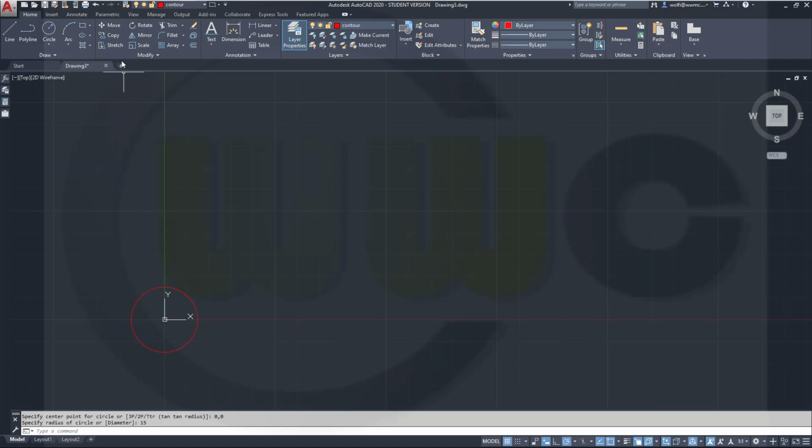Therefore I want to copy that circle. So go for copy, select that circle, right click to confirm the selection, and then you could click anywhere like this, and as your polar tracking is on, you can move along that trace, and the distance along that trace should be 60, and escape or return to finish that command.